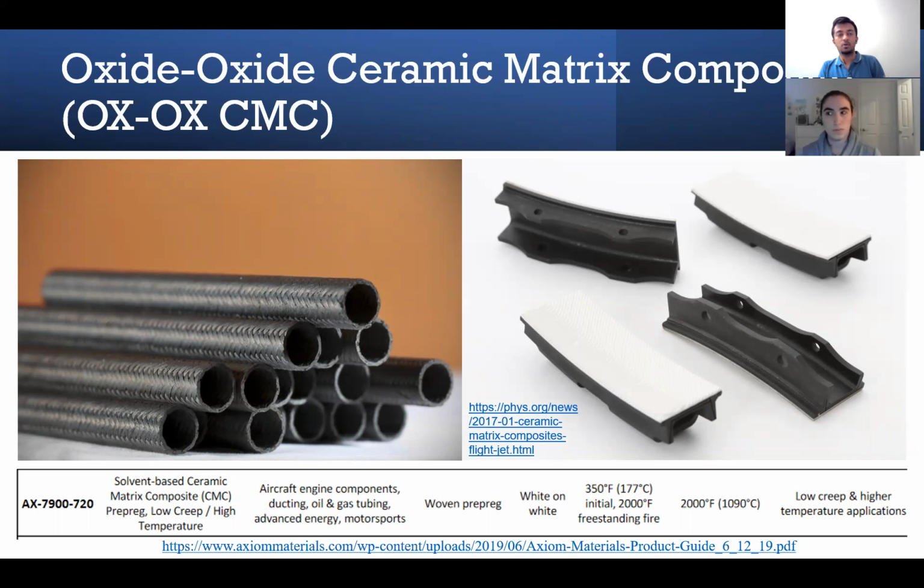So they can go up to 1400 degrees centigrade, which is pretty high compared to the materials currently being used. But one of the drawbacks of this material is that it is quite brittle. That's why it has been quite difficult to use them extensively in jet engine applications. Now the research is ongoing about how to improve their machinability, to convert them into the shapes actually required and desired for application in the combustion section of the engine.